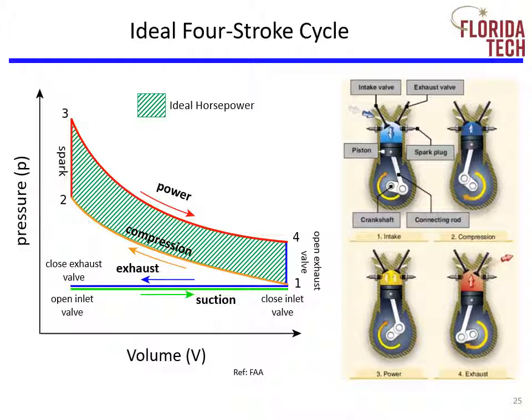But what controls those valves? The answer is the camshaft. A camshaft is a rotating cylinder situated above the crankshaft with various oblong lobes protruding from it. These lobes push on rods that connect to each valve, pushing them open. The valves are spring-loaded and will return to the closed position as the camshaft lobes move away from their respective rod.